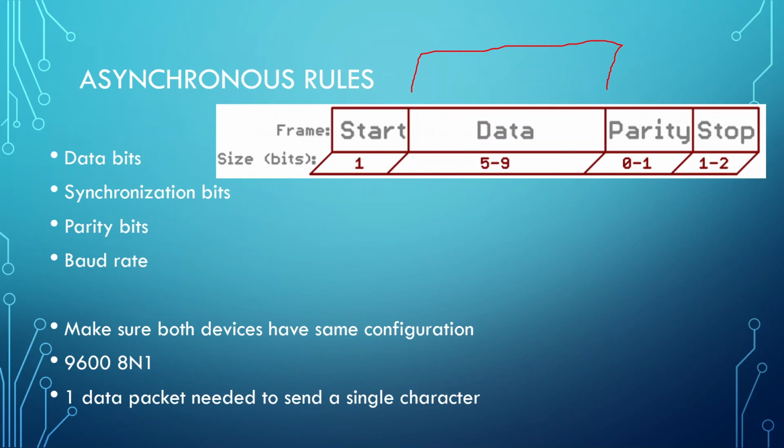We like talking about bytes. I like being able to say, here's a whole byte of information for you. Again, the most important part is that both devices are configured the same way. If I say I'm going to send you 8 bits and you think I'm only sending 6, everything becomes haywire. So having those devices set up the same way is the important aspect.